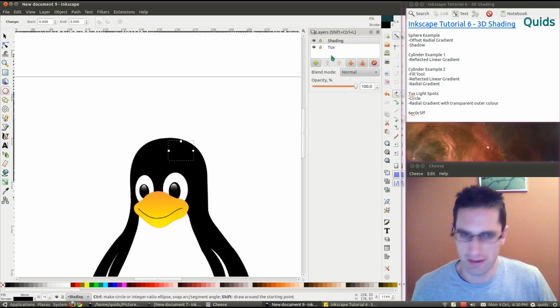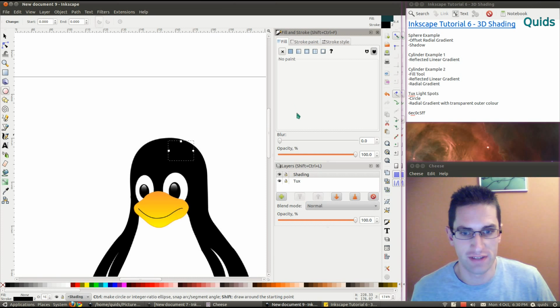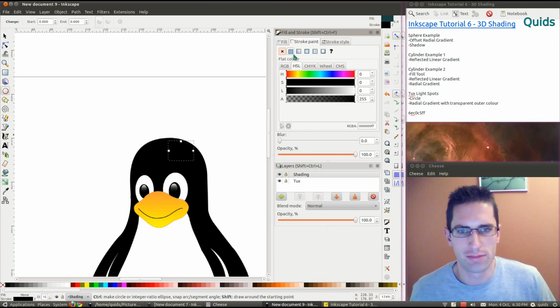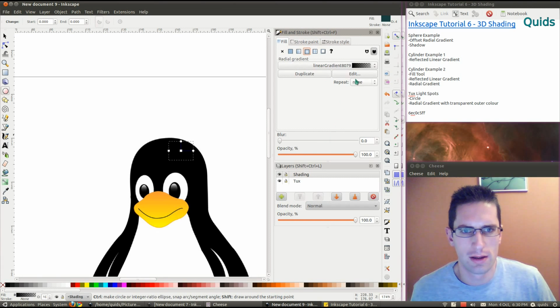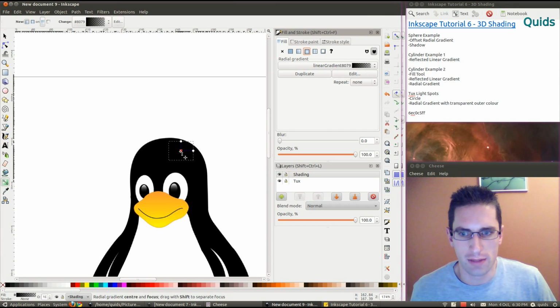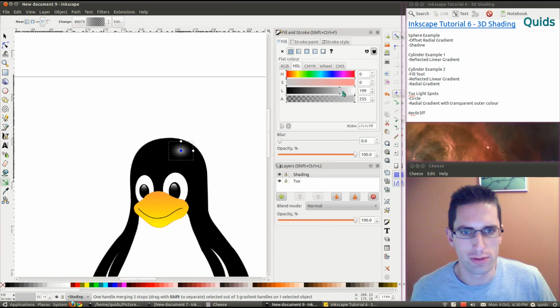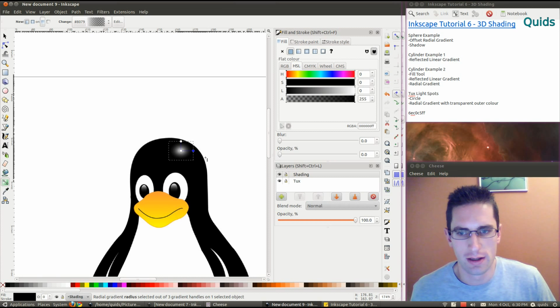So we'll just take the fill box, Control Shift F. What we want to do here, we want to turn the stroke off and put a fill on there. Now it's defaulted to black again, so you still can't see it. We click the gradient and we'll choose white. At the other end, we want opacity 0. We don't actually want to see that bit.